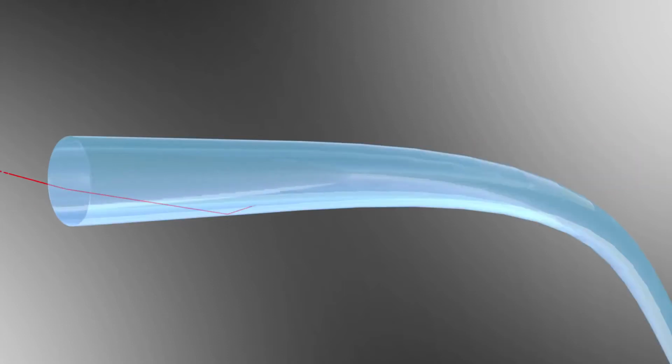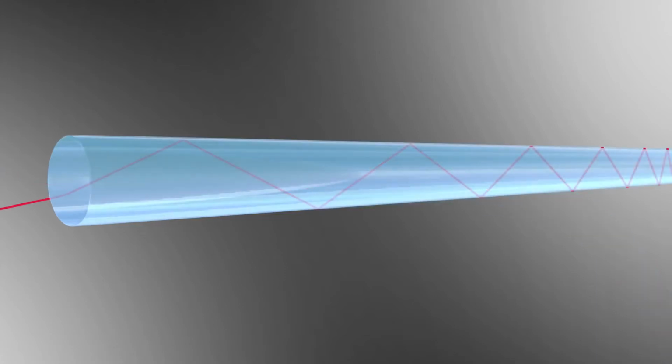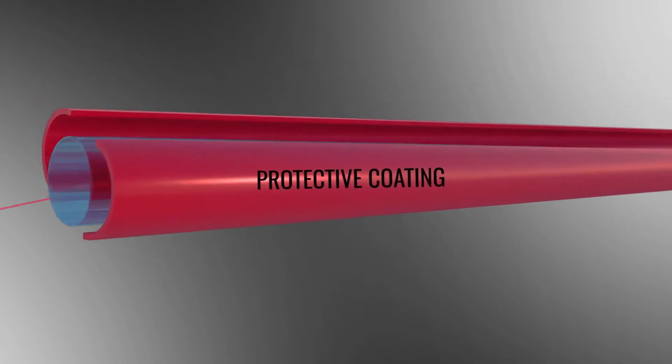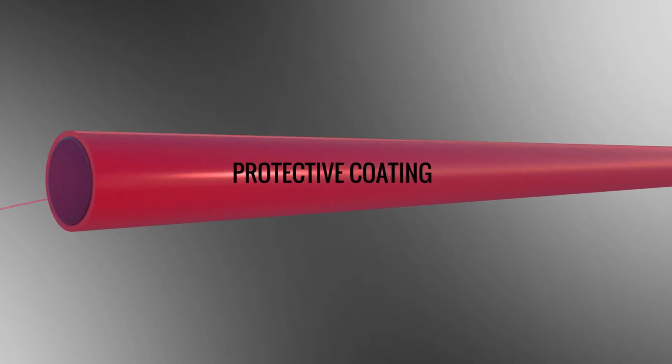This means that light can be confined in the optical fiber over a long distance, no matter what complex shape the fiber forms. Remember, total internal reflection happens between the high refractive index glass and the low refractive index air. However, optical fibers need a protective coating. A protective coating is not possible with this configuration. The introduction of protective material will replace the position of the air and cease the total internal reflection phenomenon.